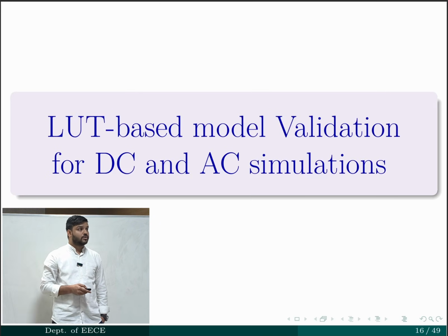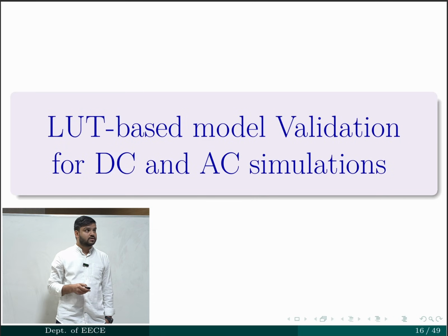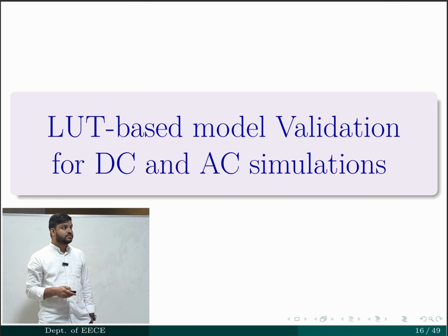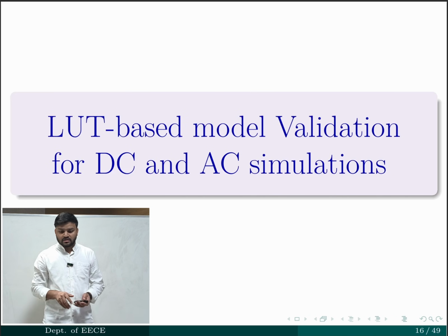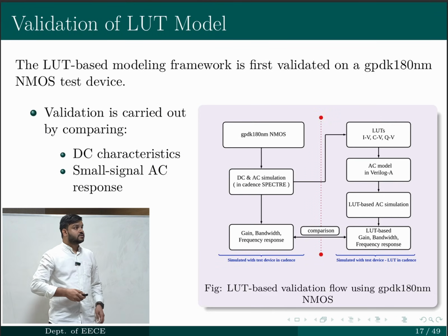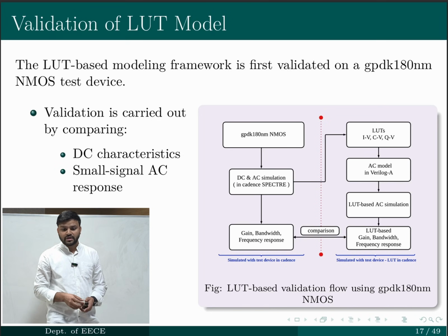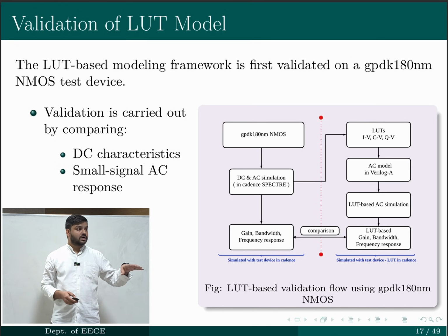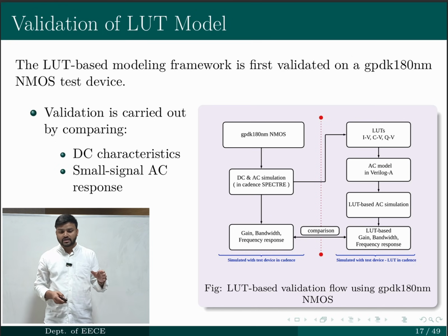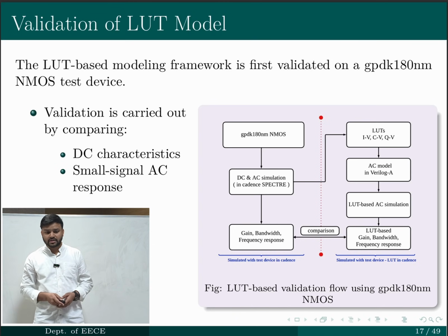Now, LUT based model validation for DC and AC analysis simulation. Before going for SGFET, we first validated the DC LUT model for a test device, which is a GPDK 180 nanometer NMOS, for which we extracted the DC and AC simulation, and from there the gain, bandwidth and frequency response are also simulated.